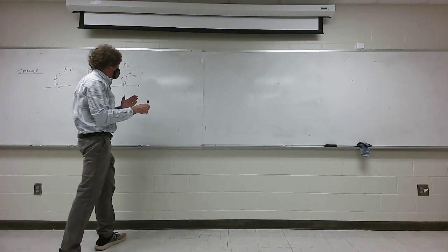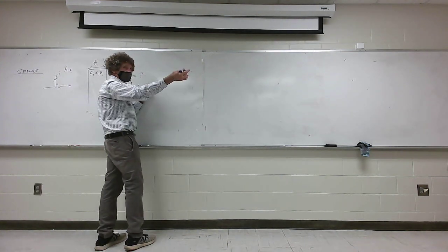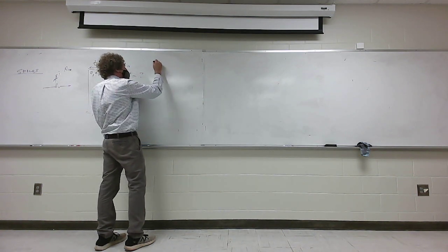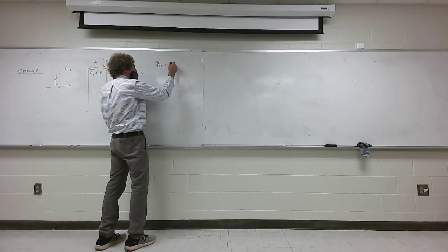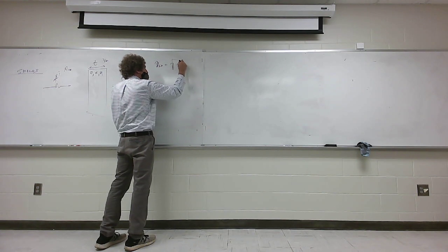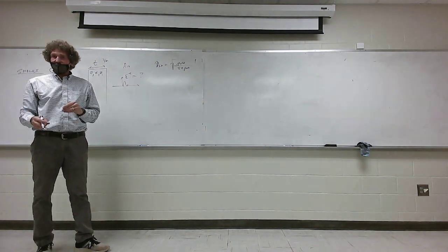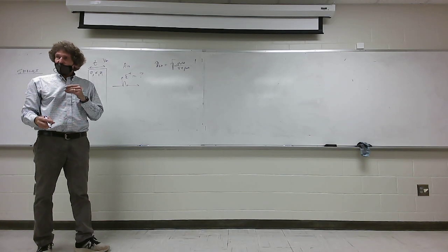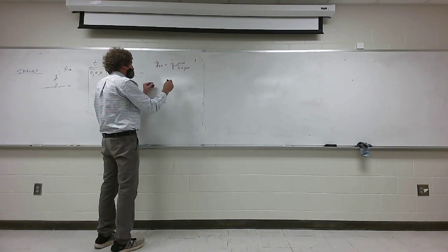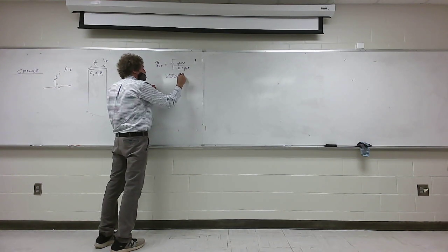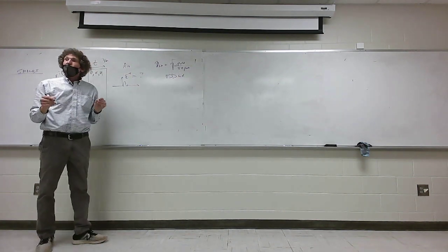The next thing we do, we assume it's at a constant frequency, so we do things in the frequency domain, not the time domain. So we talk about the intrinsic impedance eta of the shield, and that's equal to the square root of j omega mu over sigma plus j omega epsilon. Now, in realistic shields, they're real good conductors. So for realistic shields, sigma is always much, much greater than omega epsilon. Y'all follow me? Good conductors.